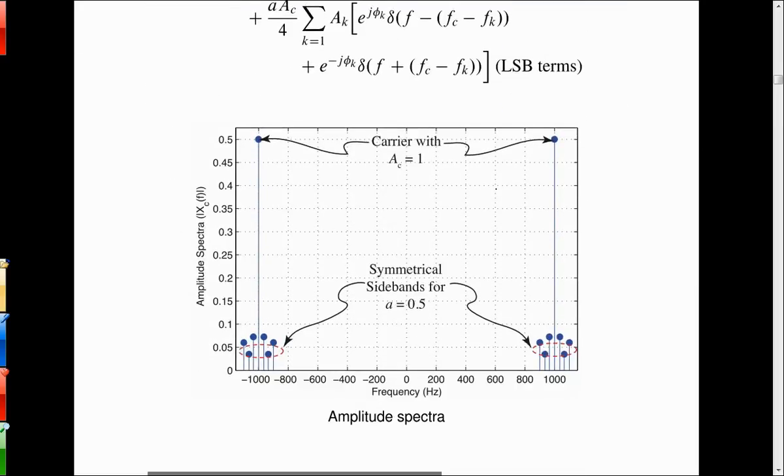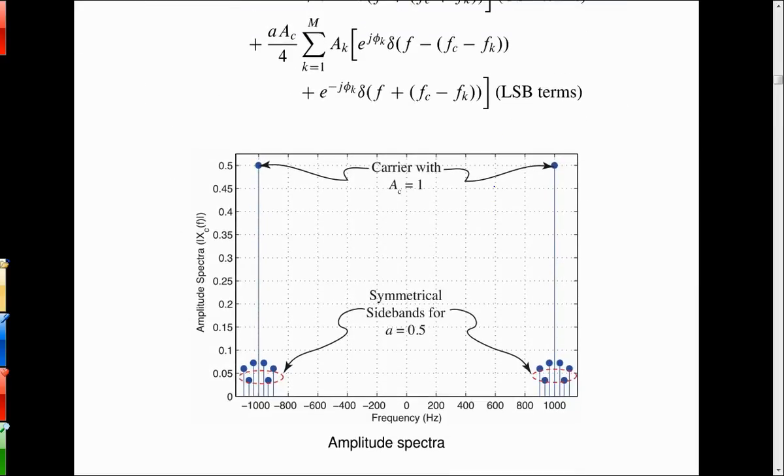And here's where I plotted it in MATLAB. So all the sidebands sitting down there look kind of like accidents sitting next to the carrier. It's just because that's the way AM works out. This is 50% modulation index. So I could double the height of those if I took A up to 1, but it's still only going to bring the values up to being in here.